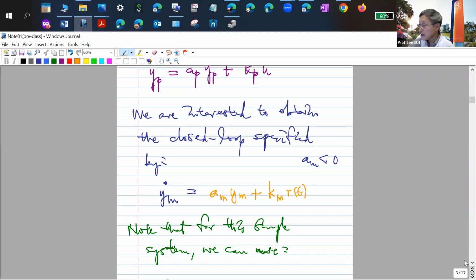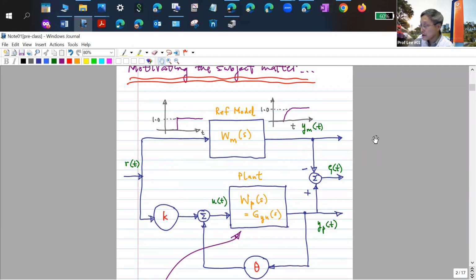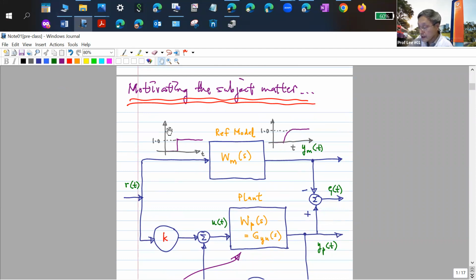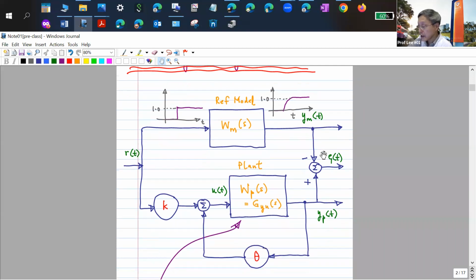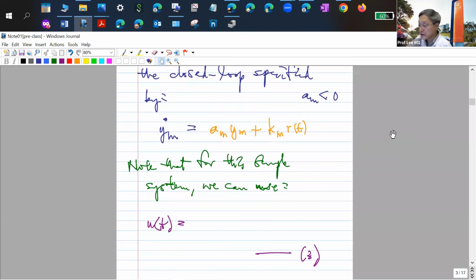It would be like that because if you look at your specification down here, you just told me that you put in a command signal moving from 0 degrees to 30 degrees, and you expect it to move like that. You've just told me the response time, and you also say you want it to move exactly from 0 to 30 degrees, which means that in the steady state, you better have unity steady state gain. That is all described in AM, which would be your response time, and KM, which would be your unity steady state gain. So that has to be described down there already.